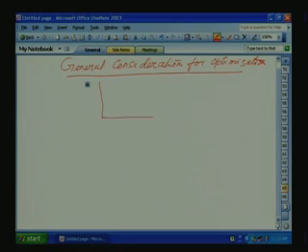So, if you see here, we want something optimized. We choose our controller such that the modulus of the gain should be 1 for as wide a range of log omega as possible. So optimization aims at bringing the modulus of the frequency characteristic as close to 1 as possible over a wide frequency range. This is also called modulus hugging.